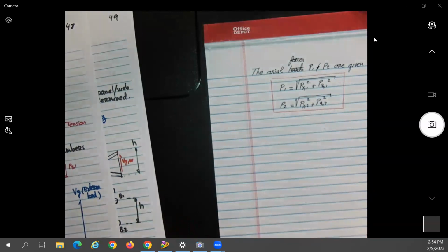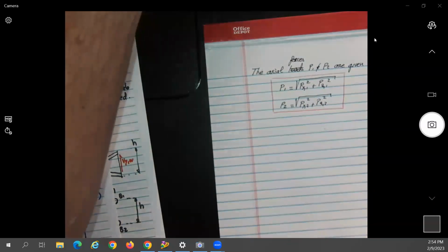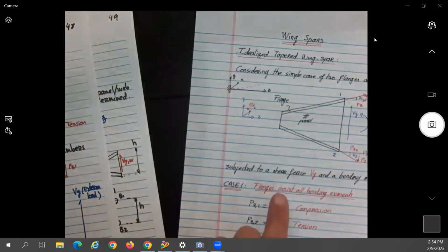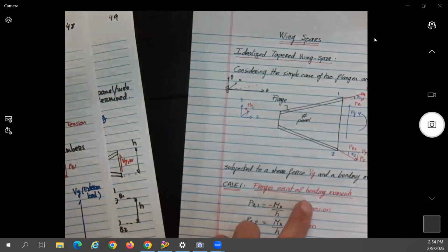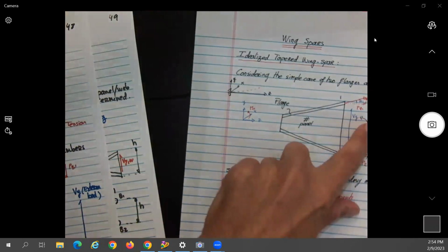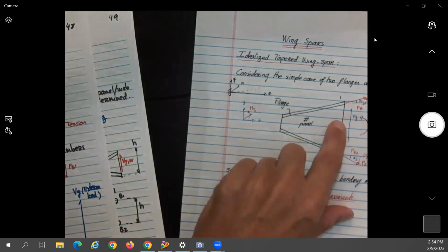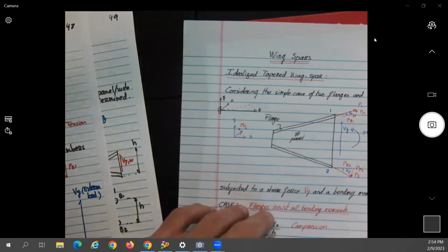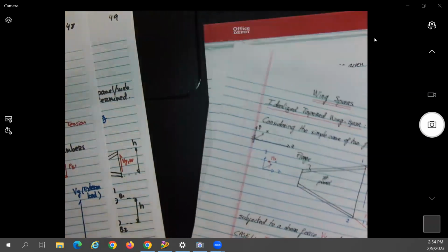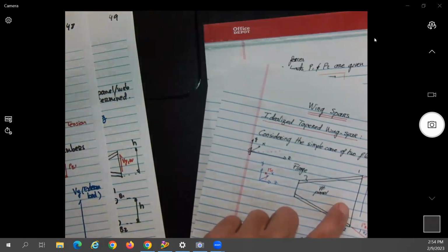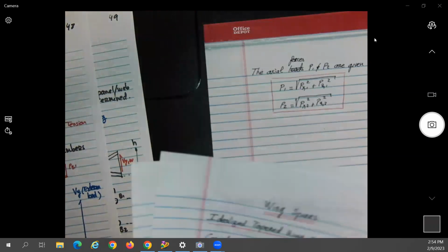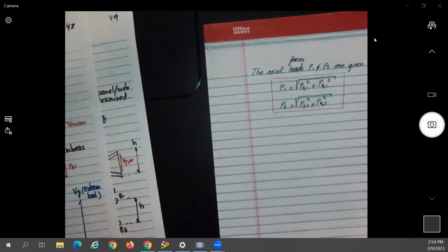Okay, so with the first part over here, with case 1 and case 2, we took care of what is going to be resisting the bending moment. So we're taking care of Mx. Now what's going to happen with Vy? What should be resisting Vy? This is going to be resisted by the panel and the flanges. There's no other option.